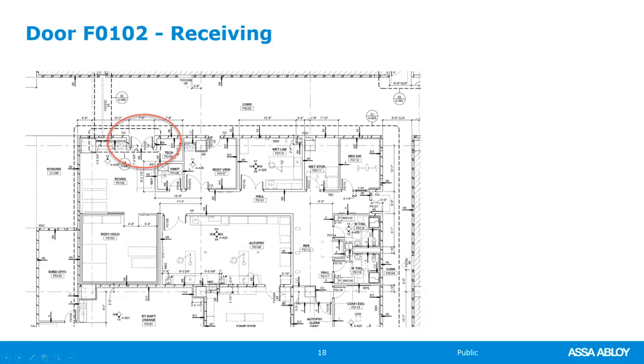these doors do swing against the wall, so I'm thinking wall stop. I do see that it's a 1-hour wall, just like the one around the corner, and it is a 45-minute rated door, fire rated opening. It's going to get a lot of use in and out, so high frequency. I'm probably going to hang this door a little bit differently.